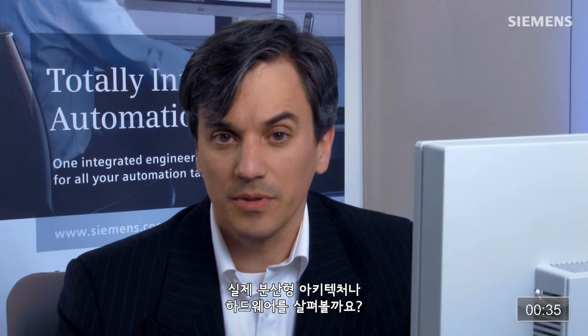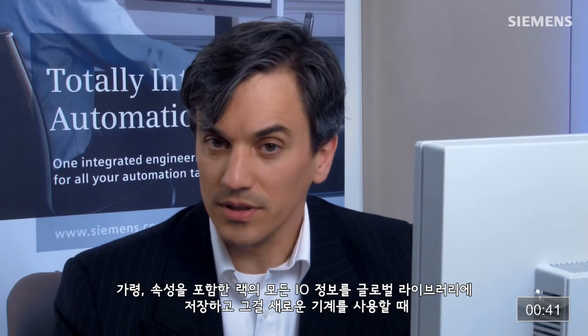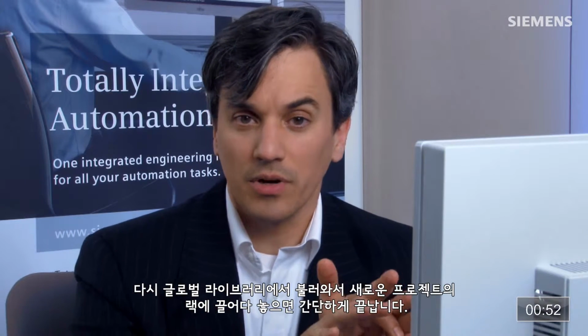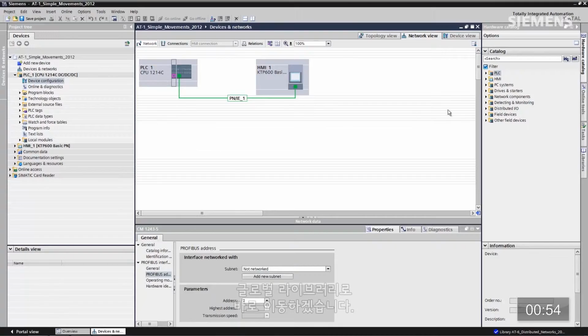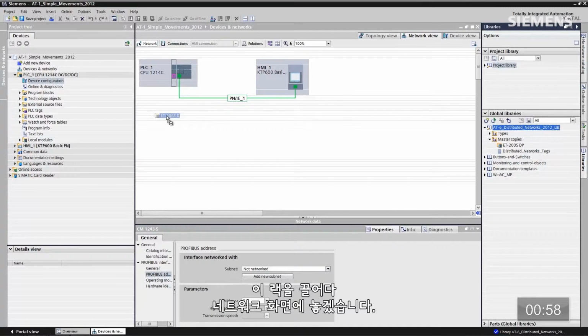How about the actual distributed architecture hardware itself? I have this E200S rack here, and I have the ability, for instance, from a global library standpoint, to save an entire rack of I/O, including the attributes, to the global library. And as I have common machines come online, I can go grab that rack, drag it in the project, and I'm done. Let's go to the global library real quick. Let's grab this rack and drag it into the network view.